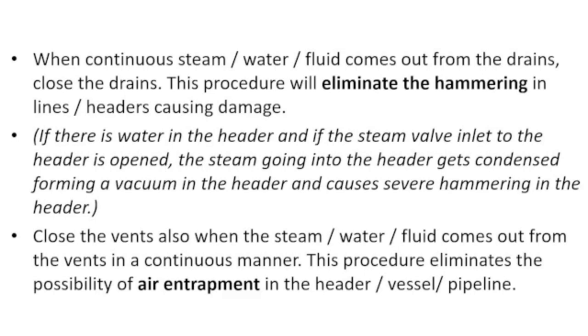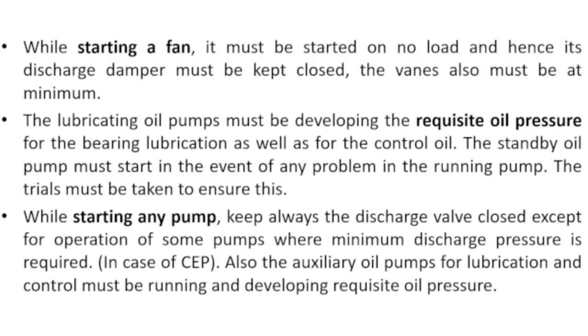If there is water in the header and if the steam inlet valve to the header is opened, the steam going into the header gets condensed, forming a vacuum in the header and causes a severe hammering in the header. Now close the vents also when the steam, water or fluid comes out from the vents in a continuous manner. This procedure eliminates the possibility of air entrapment in the header, vessel or the pipeline.